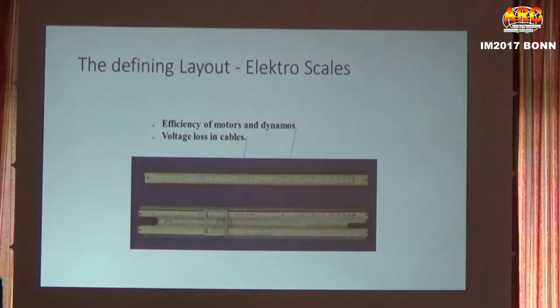Now, usually electricity companies don't get paid for reactive power. So what we try to do is increase that power factor. What we do is put in capacitors. That would give me an idea of how much capacitance I would have had to add to that connection point to bring it back to a power factor of, say, 0.9 or 0.95, which is more in line with what our standards are.